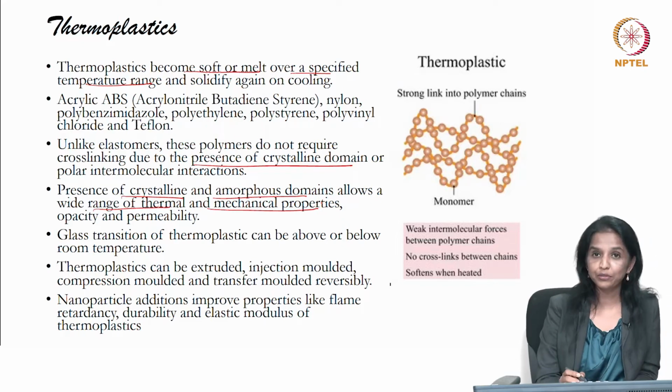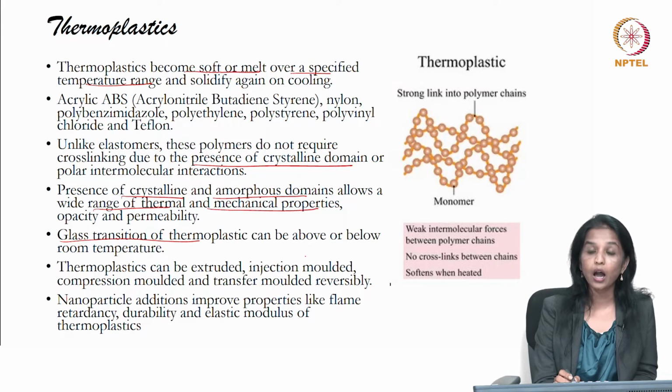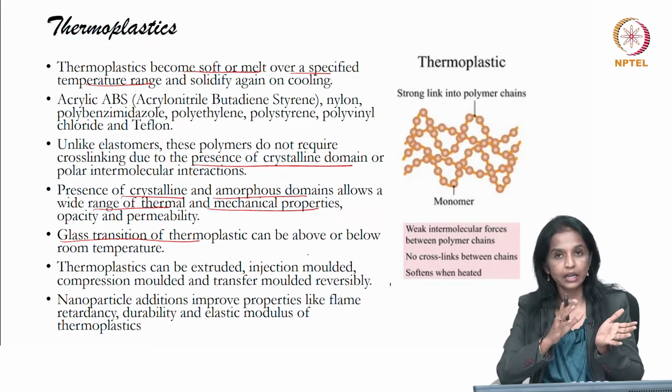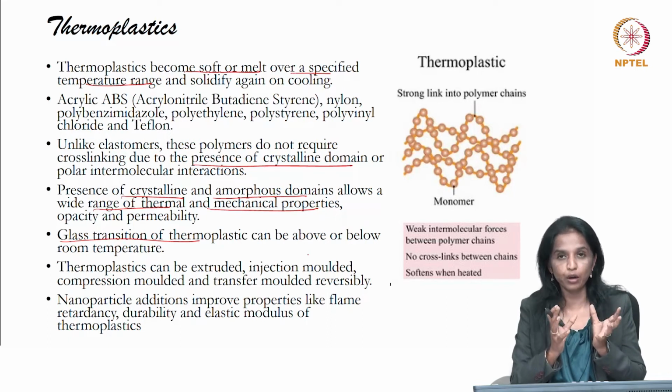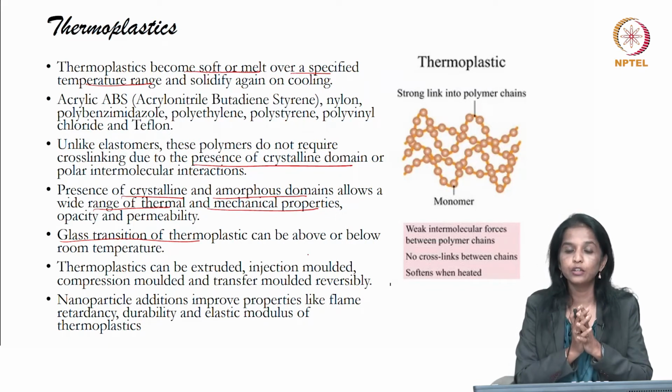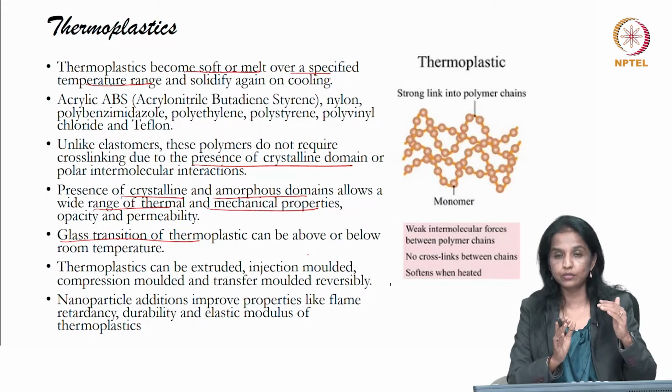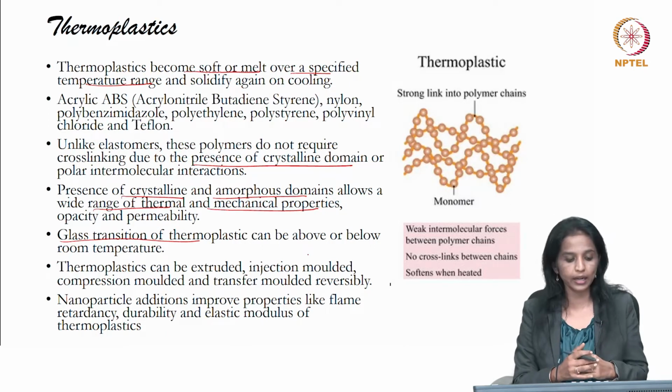And please do note that the glass transition temperature of a thermoplastic can be above or below room temperature. That is because there is again an element of amorphous structure within. So the glass transition temperature is almost similar to your elastomer.